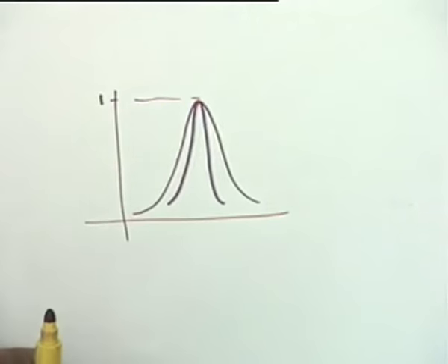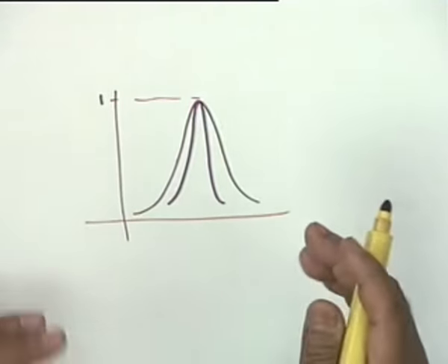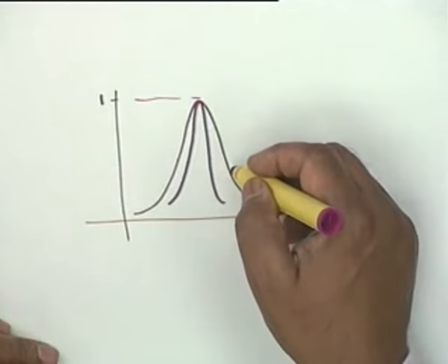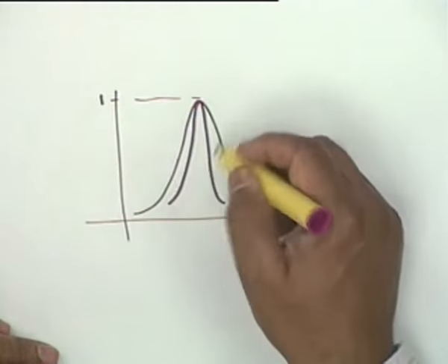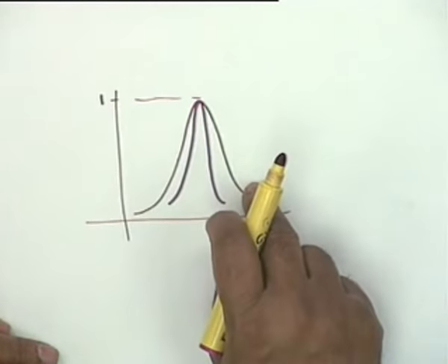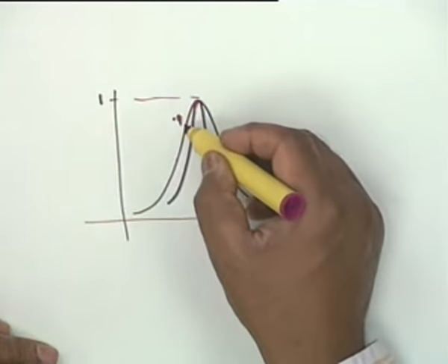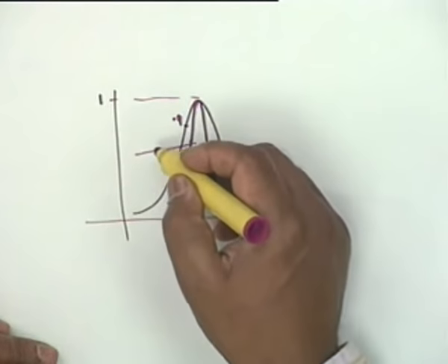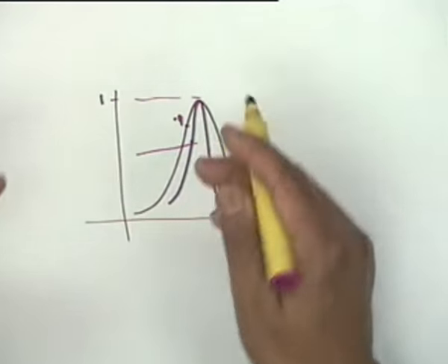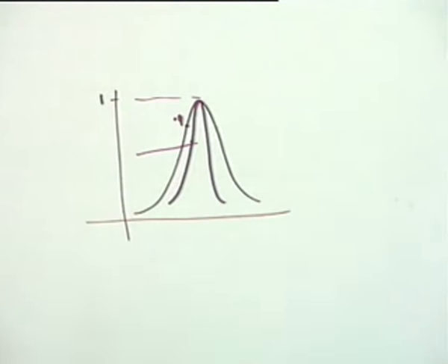If you connect 2 such stages in cascade, then the resonance frequency remains the same. This characteristic will be the square of the other characteristic, which means that wherever there was 0.9 would now become 0.81, and therefore the selectivity increases.